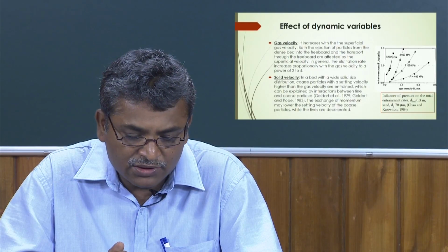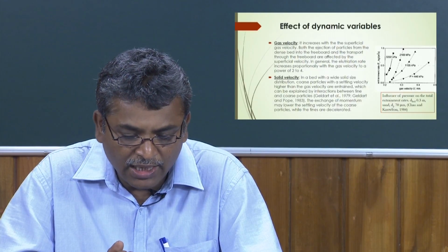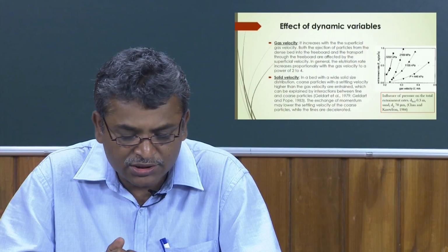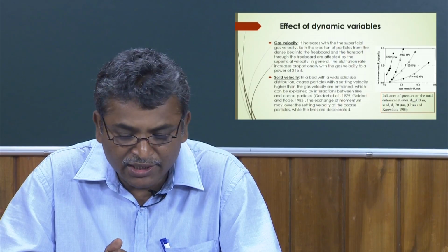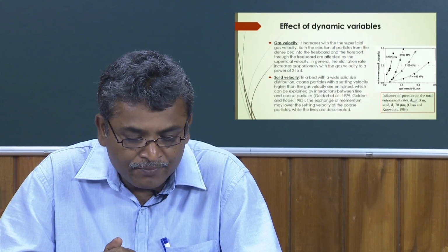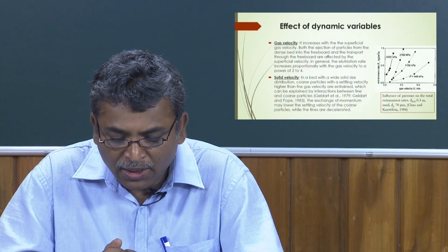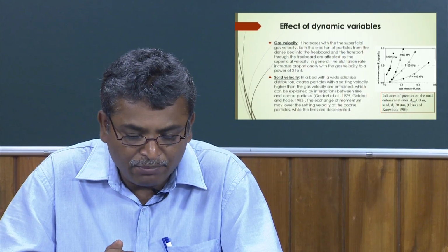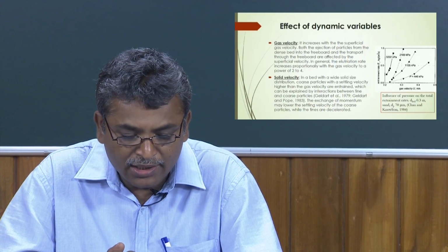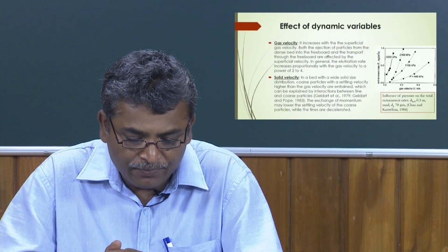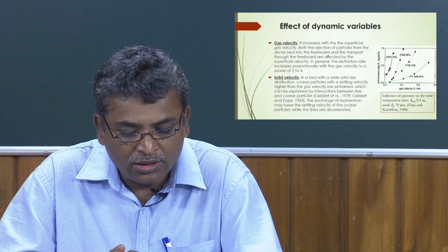When gas velocity increases, the entrainment characteristics increase, that means entrainment of solids will be higher. Both the ejection of particles from the dense bed into the freeboard and the transport through the freeboard are affected by this gas velocity.